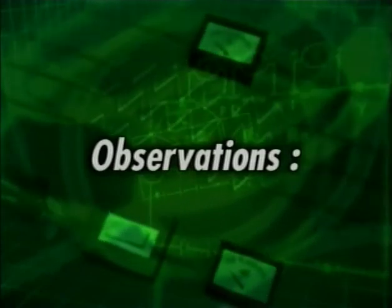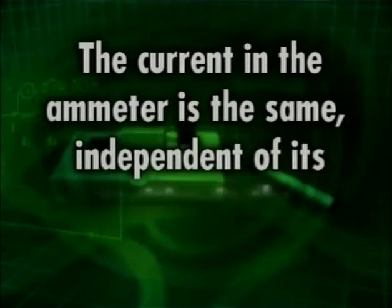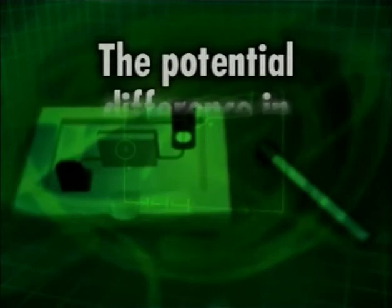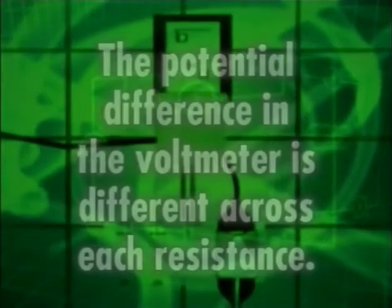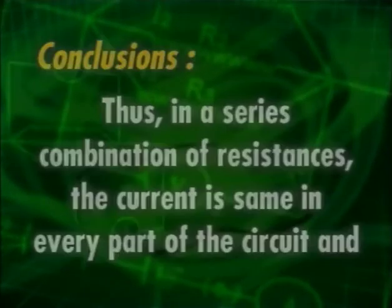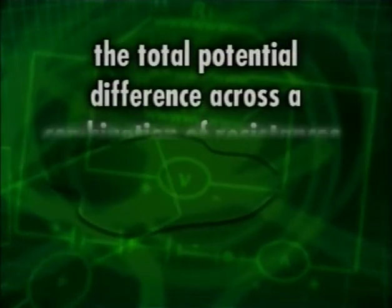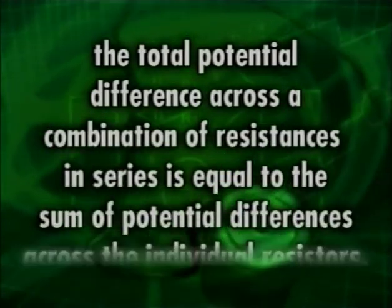Observations. It is observed that the current in the ammeter is the same independent of its position in the electric circuit. The potential difference in the voltmeter is different across each resistance. Conclusions. Thus, in a series combination of resistances, the current is the same in every part of the circuit, and the total potential difference across the combination of resistances in series is equal to the sum of potential difference across the individual resistors.